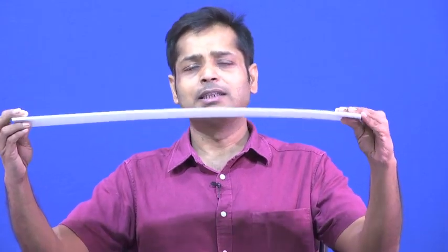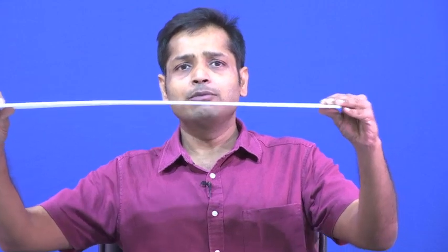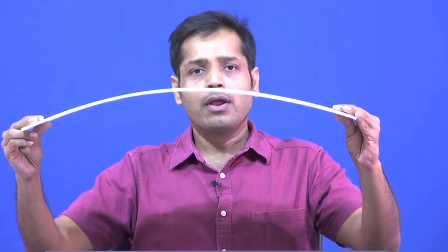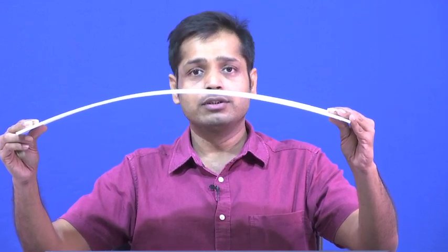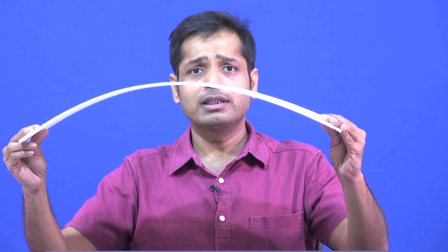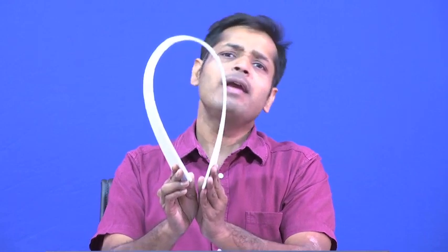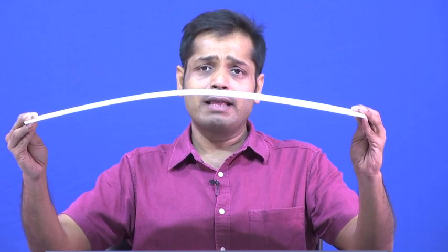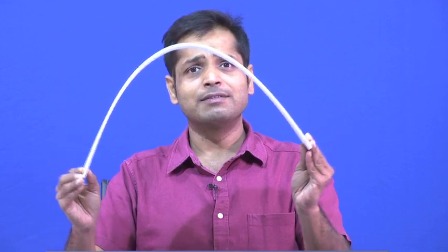Now, for instance, suppose this is a plate. If I apply some torque here at this point and also at this point, then it undergoes deformation like this, right. Now, if I keep on increasing the moment, the deformation increases, and at some point of time we may have a deformation like this. Why am I showing this example? Because when the deformation was like this, it was a very small deformation, right. But if I keep on increasing the load, the deformation increases until it is such that it cannot be treated as small.